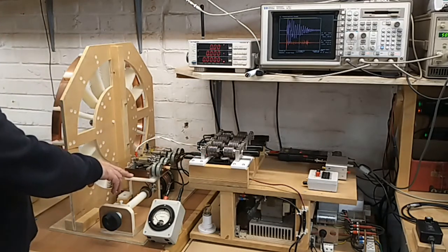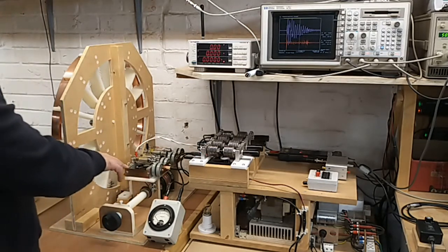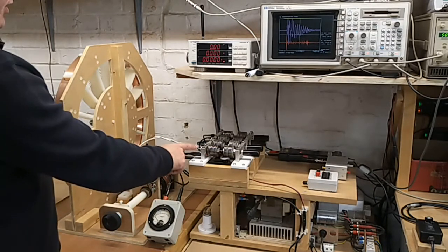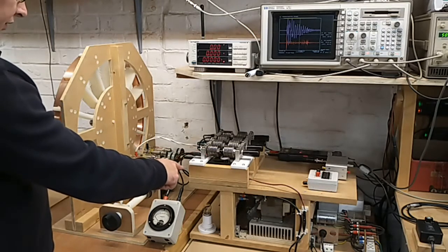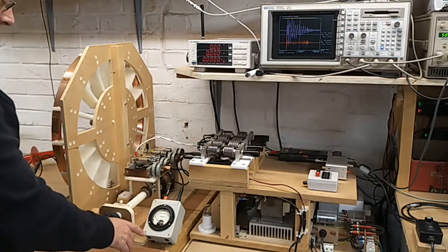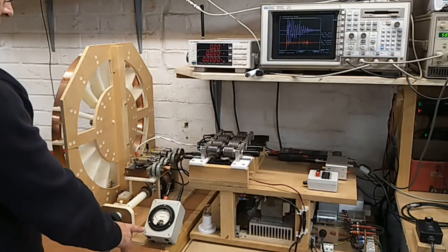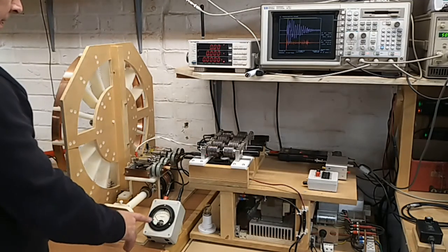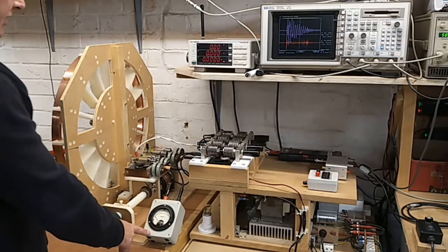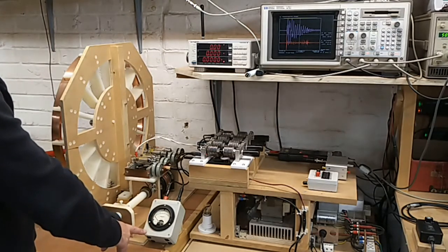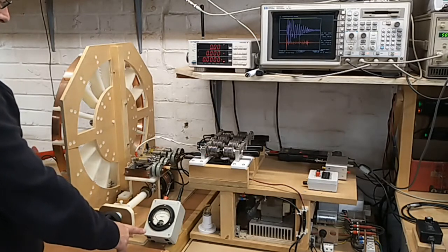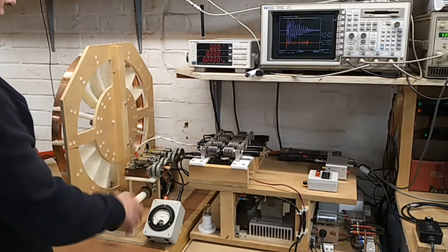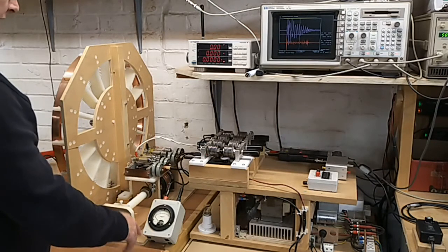We're using the tuning circuit again as in the previous experiments, but this time we're using more of the input features. So from this side we come out of the spark gap, we go through a 5 amp RF ammeter, that's a Western 425 thermocouple meter, so it measures the average, the RMS of the RF current, which is quite important to do when it's a very broadband spectrum like this.